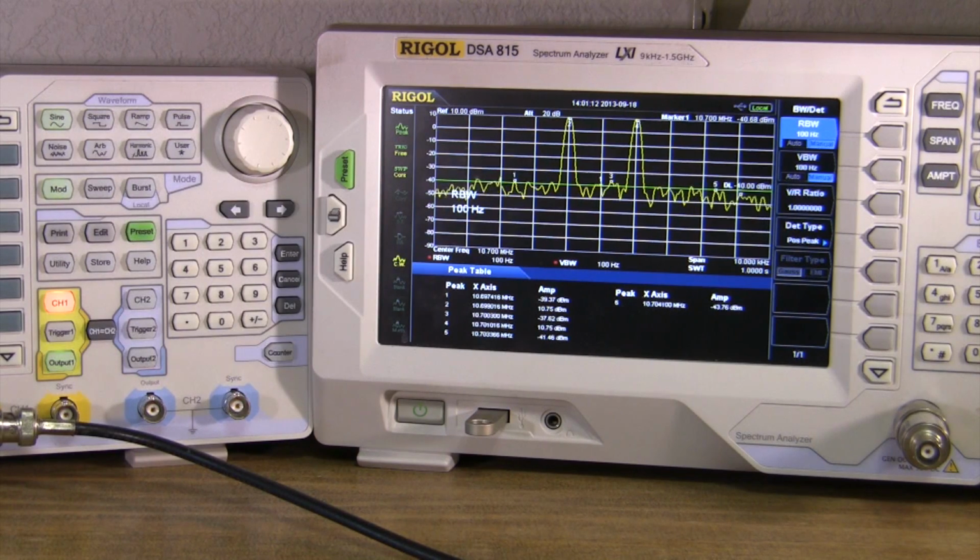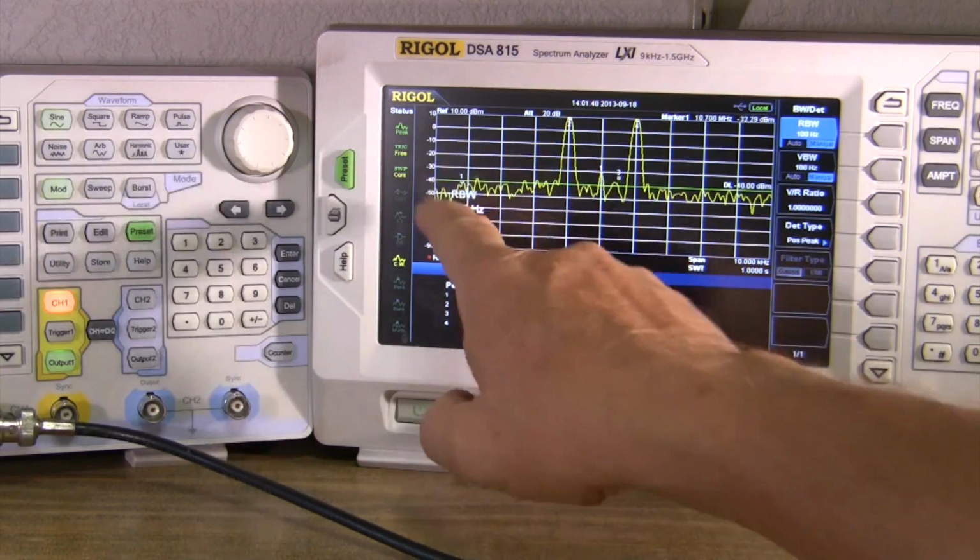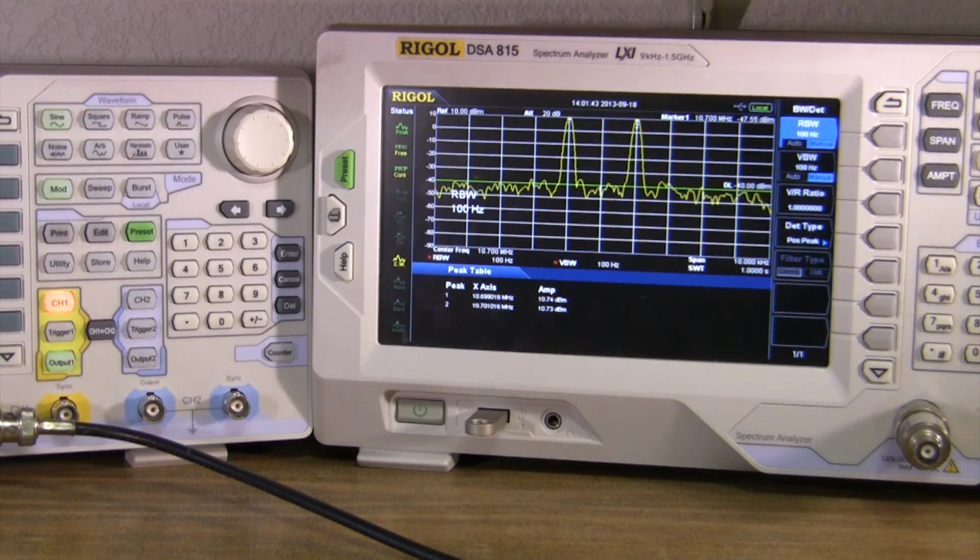And you notice that we still don't have any distortion based on the two tones here. Everything else is just noise, and that's what's peaking around -40 now. And that's actual noise of the, I would presume, 4102 here. It's 40 dB down. But anyway, the point is that you don't have intermod products out here and out here. So it's a very clean signal, and one that I would think would be very useful for a source in an IF amplifier, especially a linear type amplifier where you want to look at linearity and so forth.